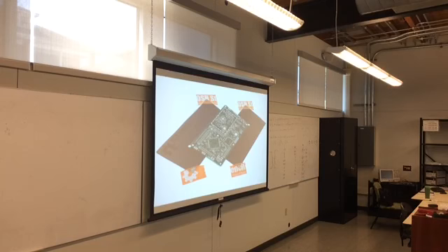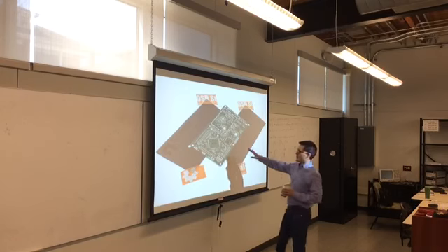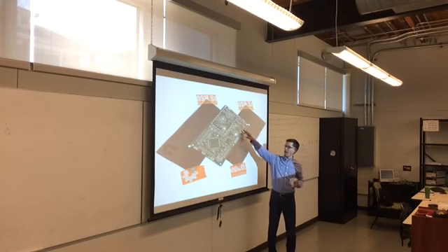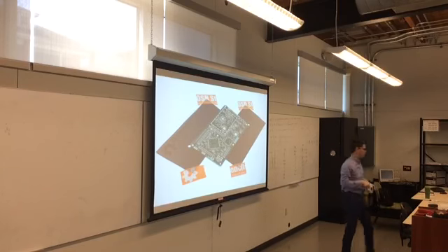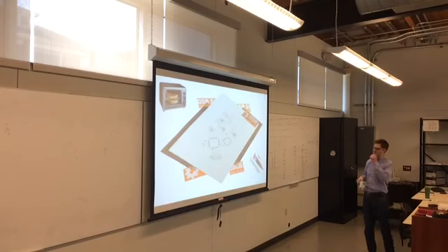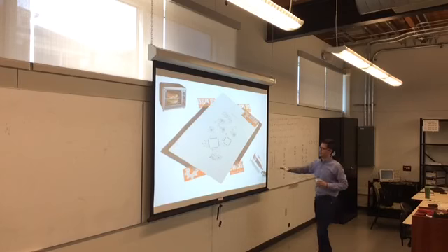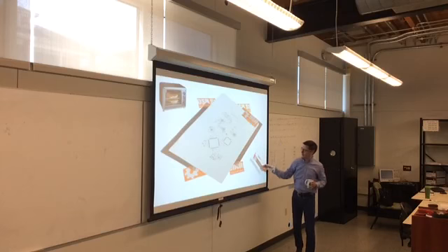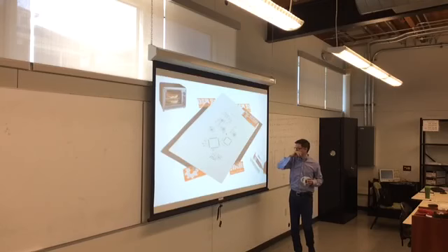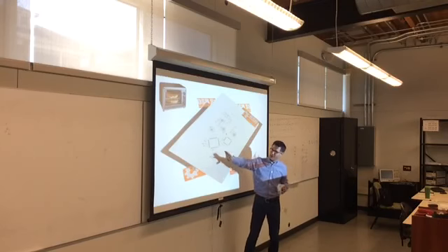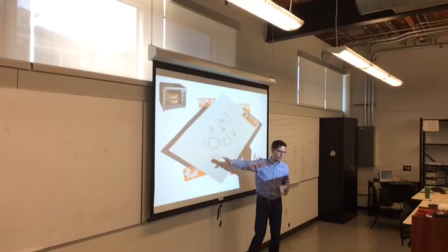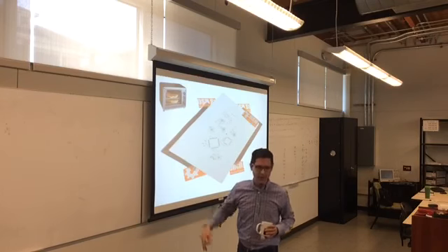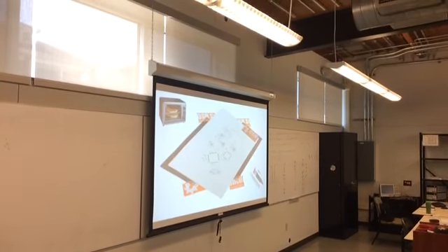I think the better way to do it is to take your board, and as we saw with Ashleen's, lay it down here in sort of the jig, and then put the stencil over top of it. And so you'll take the stencil, you'll tape it down over top, you'll take the solder paste, which is not drugs, it's solder paste. I don't know why they give you a needle. It's got a needle. And you just place the solder on the board, and then you smear it across.